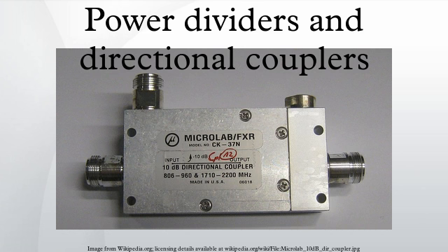Schwinger reversed phase coupler. The Schwinger reversed phase coupler is another design using parallel waveguides, this time the long side of one is common with the short side wall of the other. Two off-center slots are cut between the waveguides spaced λ/4 apart. The Schwinger is a backward coupler. This design has the advantage of a substantially flat directivity response and the disadvantage of a strongly frequency-dependent coupling compared to the Bethe hole coupler, which has little variation in coupling factor.